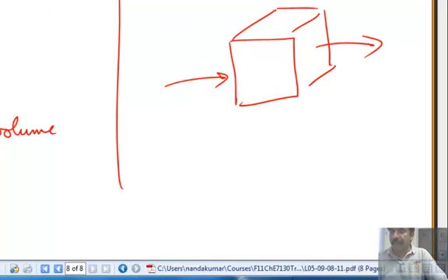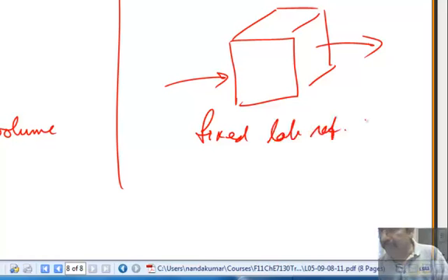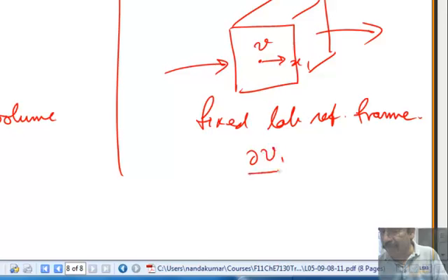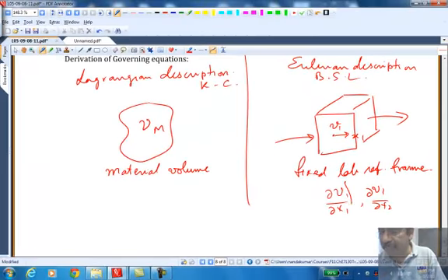Now, in an Eulerian reference frame, we are saying that this is a fixed lab reference frame, whereas the material frame is a moving one. It is moving with the object. Now, if I am observing the velocity of a fluid that is going through that, its change in the x1 direction, for example, I will define my conventional dv1/dx1, dv1/dx2, etc. This means I'm keeping everything else constant.